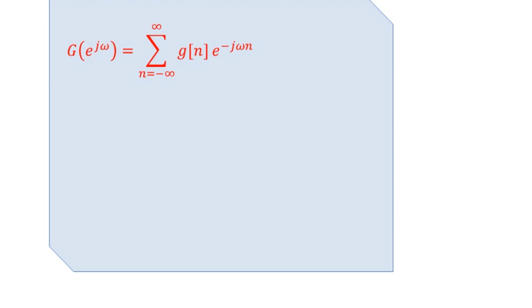So this DFT can be denoted as capital gamma of k. For providing a sufficient resolution, the DFT length capital R is selected to be greater than the window length that we generally denote by capital N, and this is to be done by zero padding the windowed sequence with R minus N zero valued samples here. And the methodology for carrying out the discrete Fourier transformation is usually the FFT algorithm.